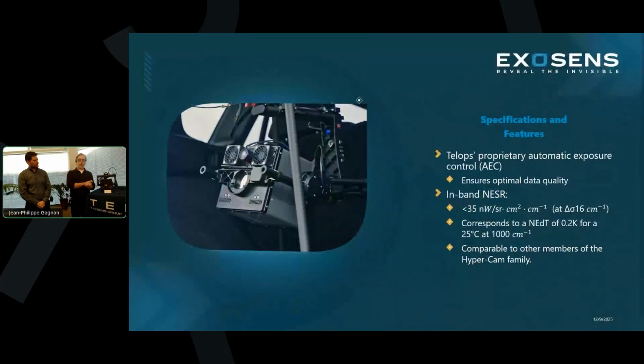Of course, we're using the permanent calibration. That brings about another advantage: the Nano operates with an automatic exposure control. You remember from the first few slides, the instrument collects several images of the intensity with a specific exposure time. If that exposure time isn't set properly, you're at risk of saturating or underexposing the image. So it's critical that the exposure time is set properly. With the Nano, everything is done by the Nano itself based on the measurement it's doing at the moment, so it will readjust its exposure time. For the user, that means you're collecting optimal data every time. That's really important for us.